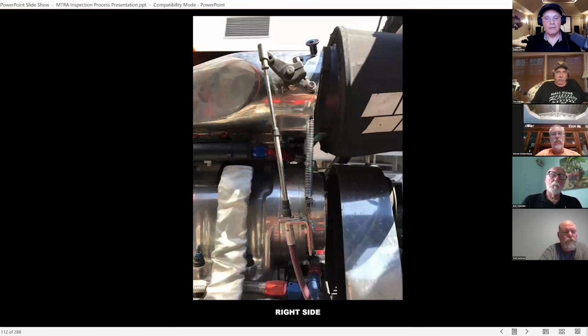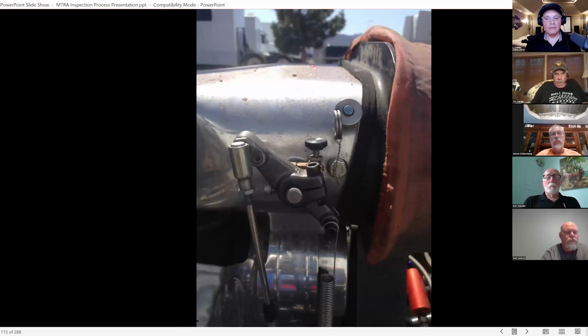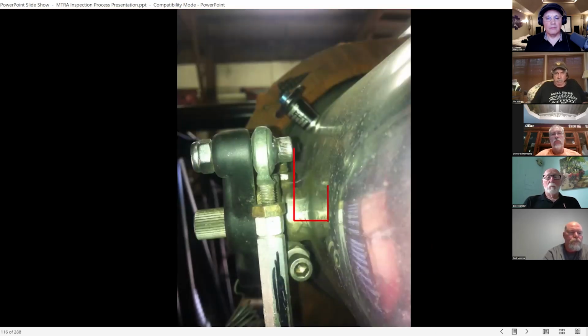And we've got to be aware of and watch the bolts, the way the screws go in there on those black arms. In this case, that screw, if there wasn't a nut on it, can back out and get against the injector hat. We've had instances where, because that injector hat's rounded, it gets out there against it. The driver's foot goes to the floor, it drags past because there's a lot of force on it, goes down past the injector hat, but it won't come back up, and it sticks. And somebody runs into the fence or whatever.